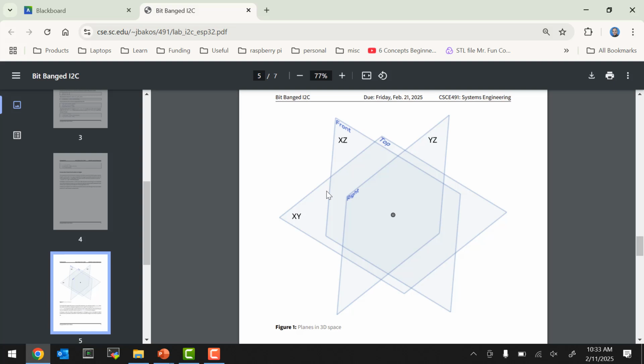So you might say, well, why do we care about angles? Well, the ultimate goal is to try to make something that balances. We want to try to make a balancing robot, essentially. And so we care about these angles. We want to try to keep this thing in equilibrium, like have it balance. So that's why we're converting these accelerations to angles. But the calculation is trivial. That's not the hard part of this lab. That's like 3 lines of code.